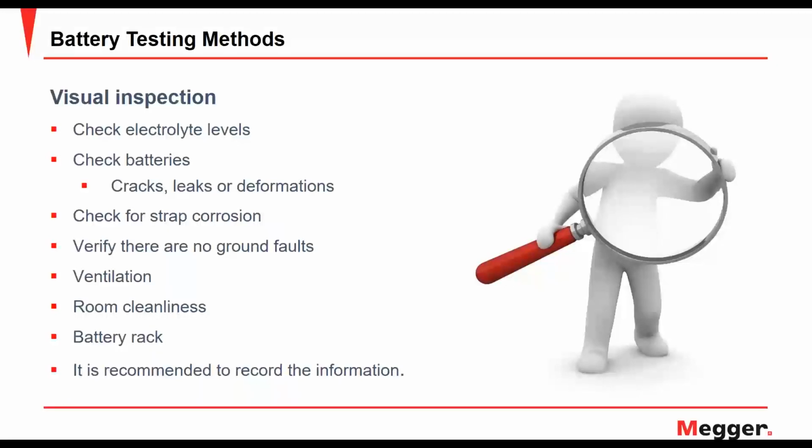For example, in sealed type batteries, you can find some expanding in their cells, thus indicating a drying out process happening. So verify that there are no ground faults or leakage currents, and having good ventilation and room cleaning is very important for the flooded type lead acid batteries.